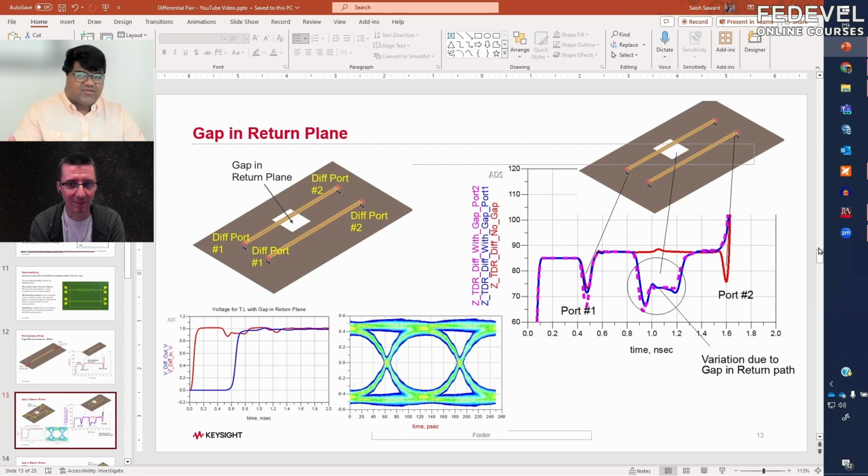Okay, interesting. It means when you do this TDR analysis, you need to know what you are doing. Otherwise, you will see something that is not really true. Yes, and that's where using those rules of thumb, those consistency checks, using rule number 9, helps. Hey, what do you anticipate? Initially you anticipated that you should see a via, but you are not seeing that via. So why would you not see a via?